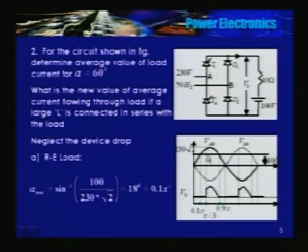It's because just prior to 60 degrees, what is the output voltage? It is E. If I neglect the turn on time of the devices, immediately after 60 degrees, what is the output voltage? It is the same as the input voltage, that is 230 into root 2 into sine 60, or sine pi by 3.